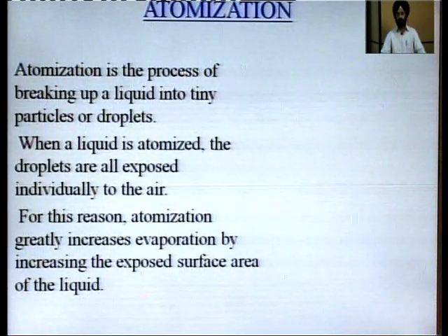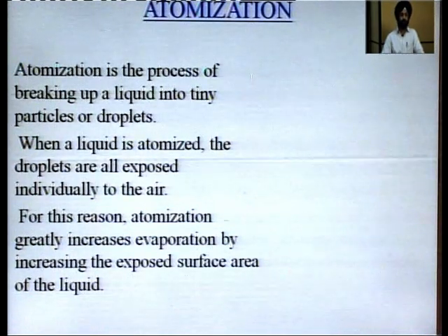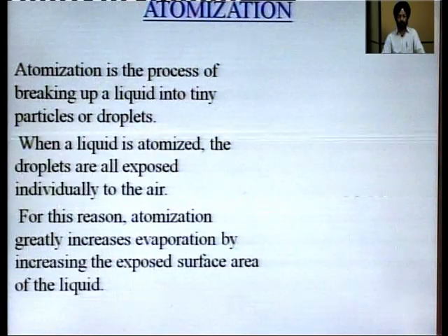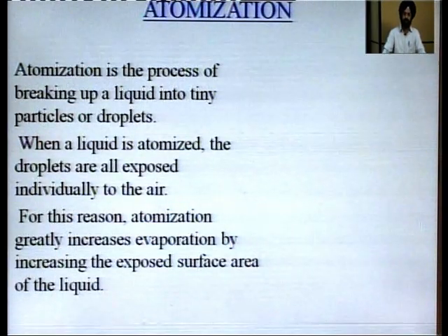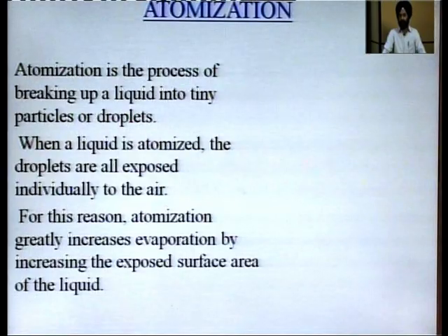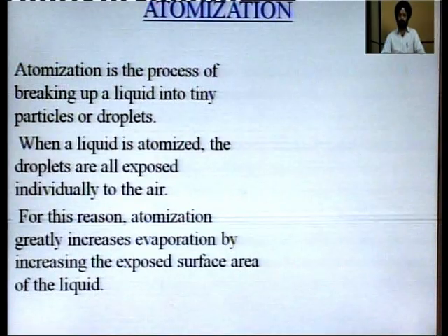The fuel is supplied in the form of liquid. If we try to burn the liquid in the engine, it will not burn efficiently. So what we have to do is increase its surface area so that it can come into contact with the oxygen in the air and burn completely to give all the energy stored in it. Our target is to burn each and every atom of the fuel supplied to get the maximum energy.